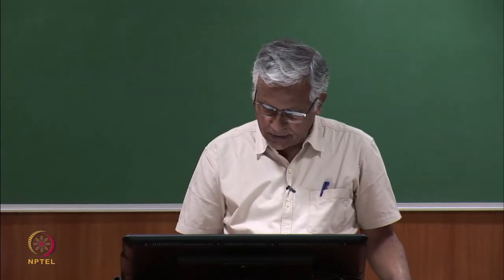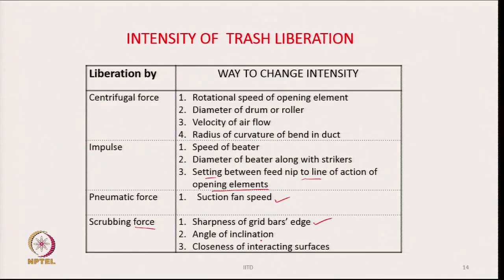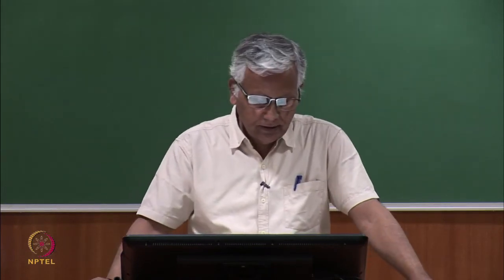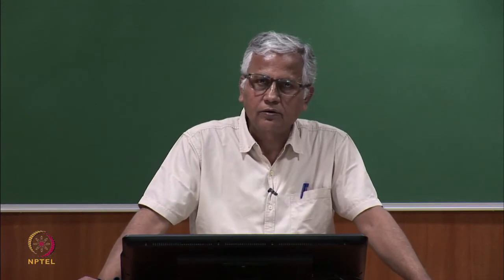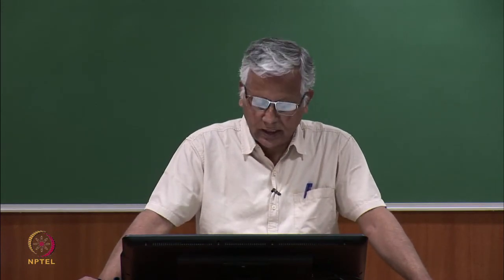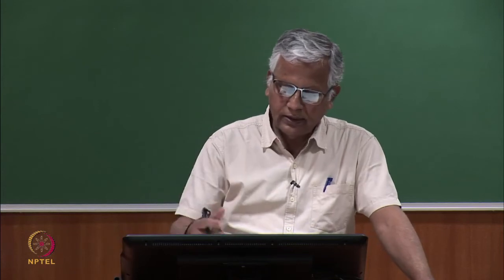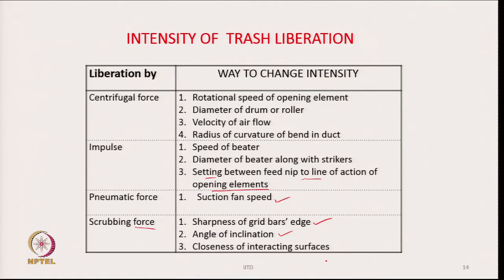depends upon the sharpness of the grid bar edge, their angle of inclination, and the closeness of the interacting surfaces, that is the tip of the striking element and the grid bars. The space between these will also decide the intensity of the scrubbing force which is acting on the tufts. So, these are the means by which we can change the intensity of the trash liberation, but